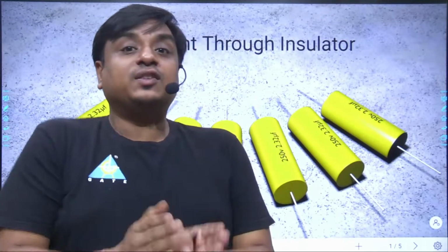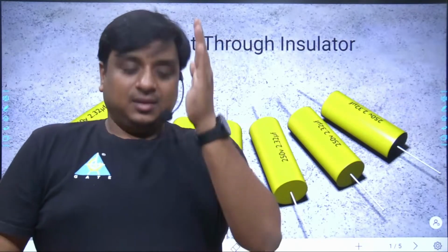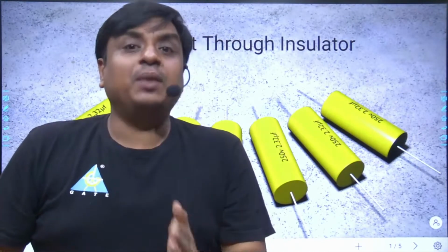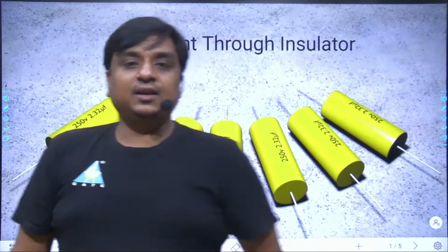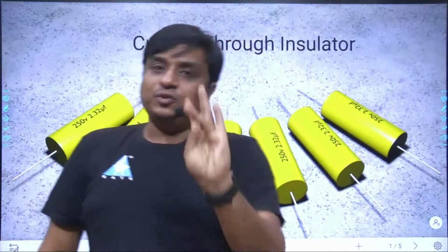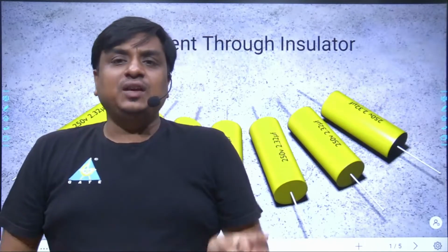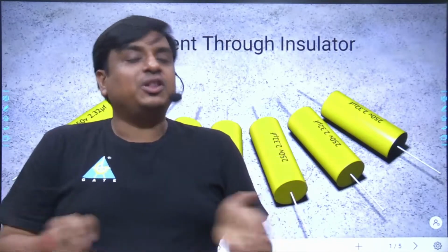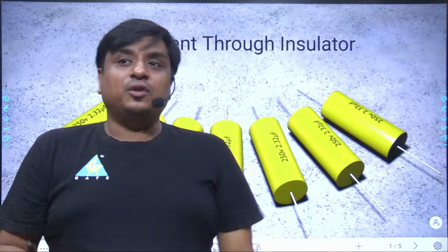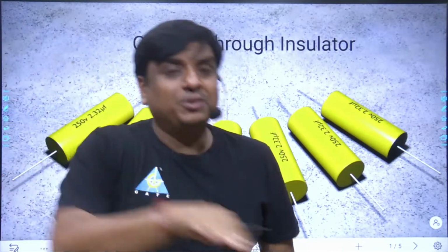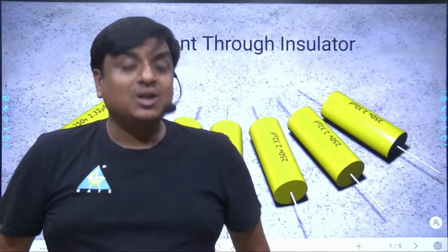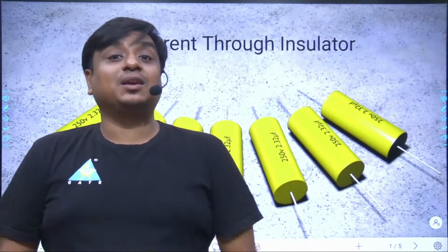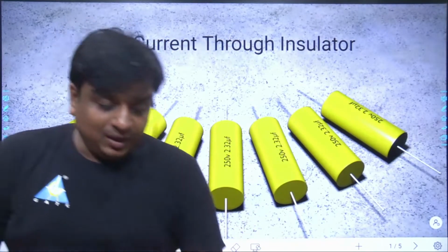There are several more kinds of currents where the charge carrier might not be flowing, but still there is the fundamental of current. You can take the reference of diffusion current, which you see in a diode, which you see in a non-uniformly doped semiconductor. There the charge carriers do not move, but still you find a current, and that current is nothing but diffusion current. Similarly, another kind of current is a convection current.